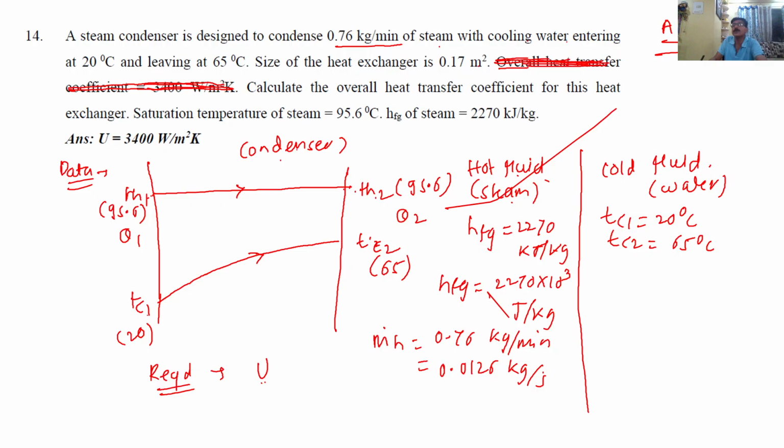So better to go step by step, just like me. 1 minus 0.5369, which I already calculated here, divided by 1 plus R, which is also known to you, 1.3822. So the answer comes at 0.3350. So this is the answer for effectiveness, and it is answer number 1.